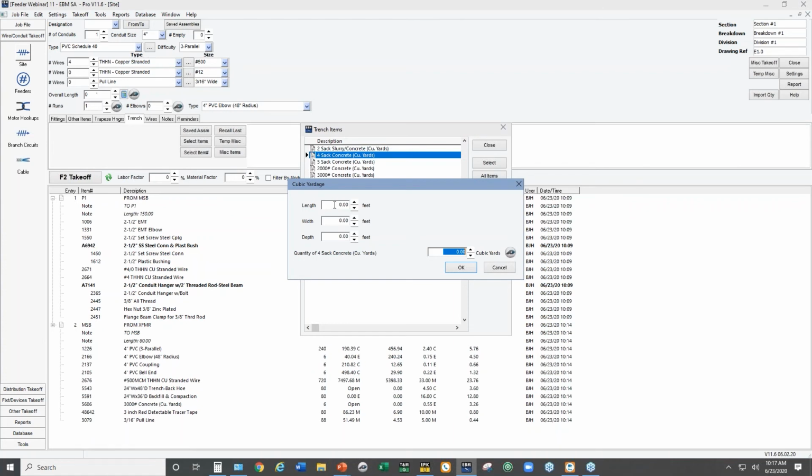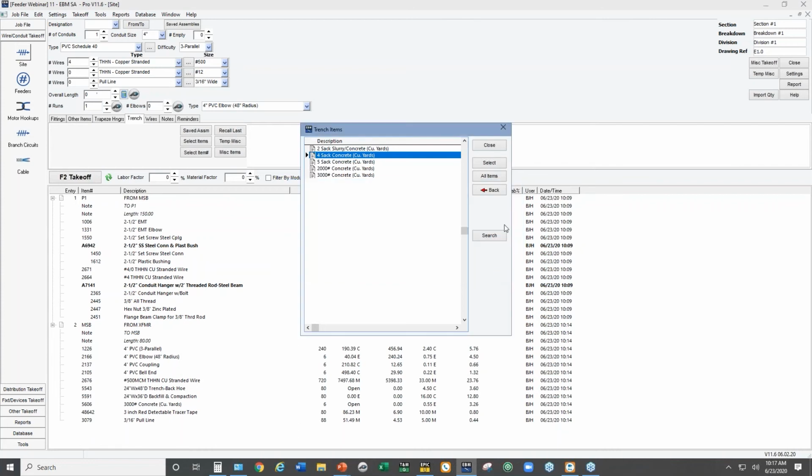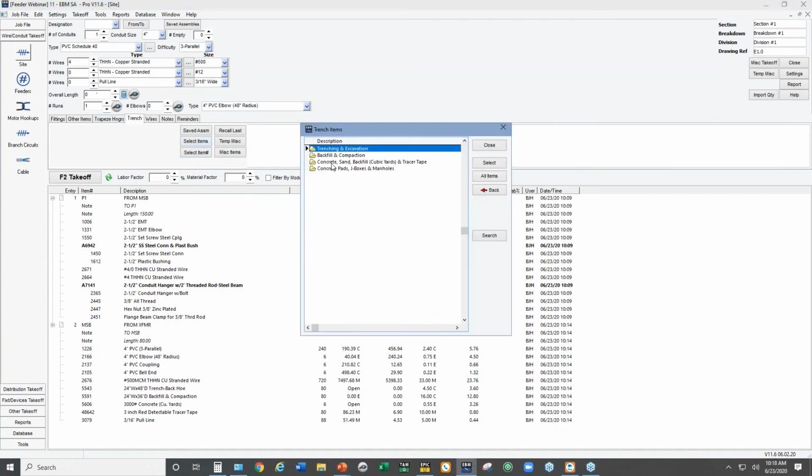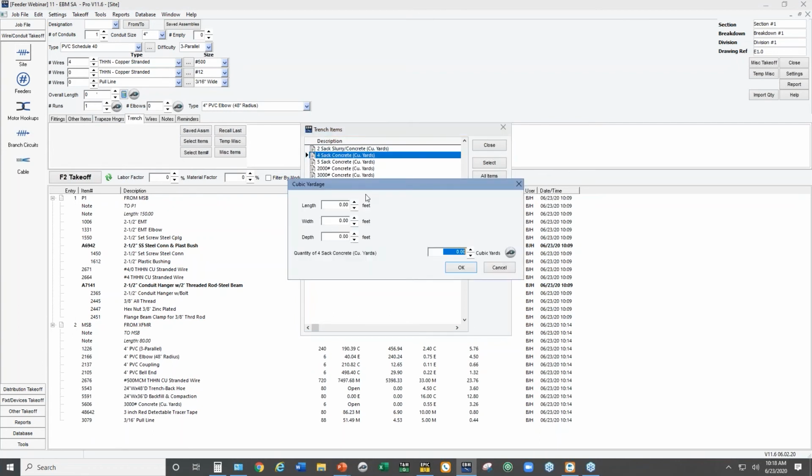You just have to manually put in the length, the same length you put up here on the overall length, and then you have to tell it what the width and the depth are. Yeah, so that's a manual thing. PlanSwift isn't going to help you with that. Let me see if there was another question there. Yeah, PlanSwift won't put anything into this field here for the length on the backfill. It doesn't fill that field. You have to manually type it in.